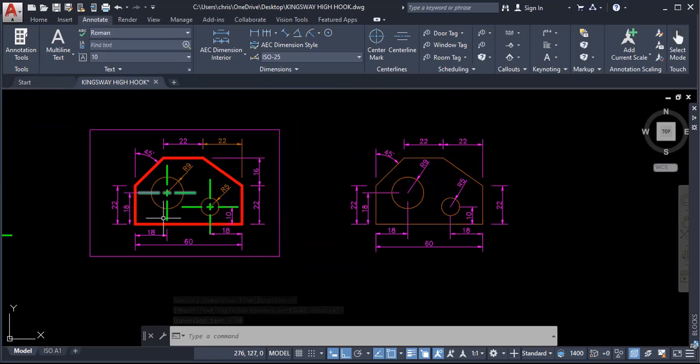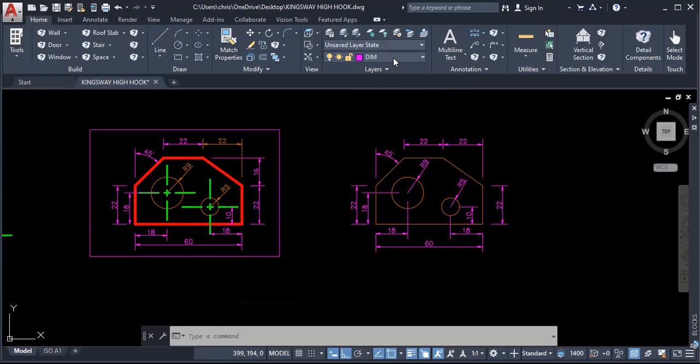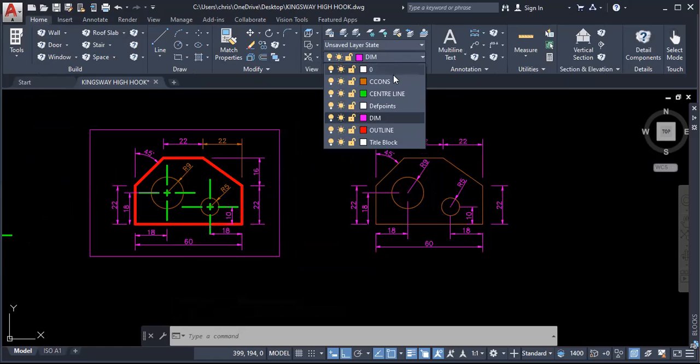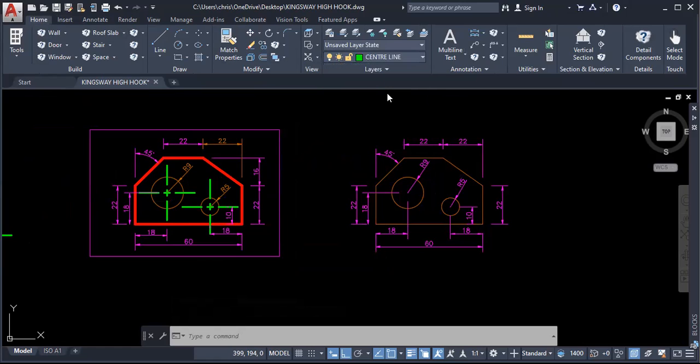You could stop, draw your centers for this, but for now, well, we could do that. Probably I should. Go to home. Center line, then draw a line, one line here. Space bar to reactivate the next line here.